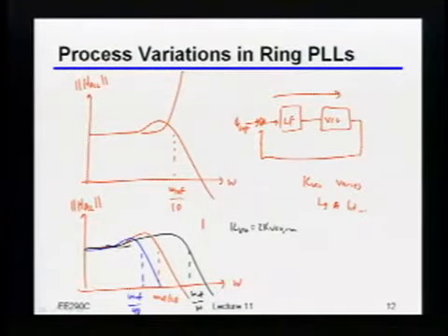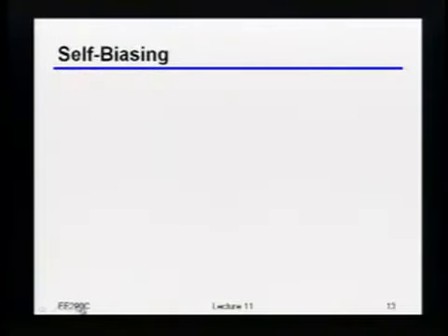Now, what's true is that, by the way, I may want to use this PLL with 10 different reference frequencies, or with 10 different output frequencies, right? So then if I start doing that, it's even worse, right? Because then I have to put the bandwidth at whatever the worst possible thing that could ever happen to me would be. And by the way, I focused on KVCO, but this loop filter varies too, right? Charge pump actually varies too. Everything varies, right?